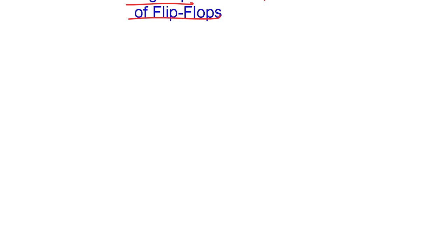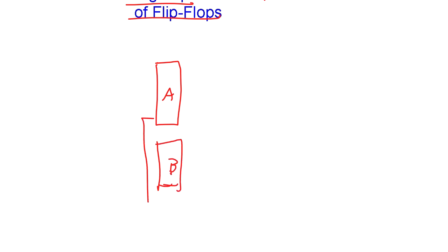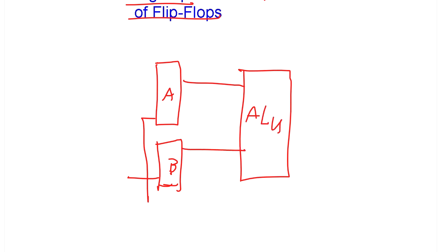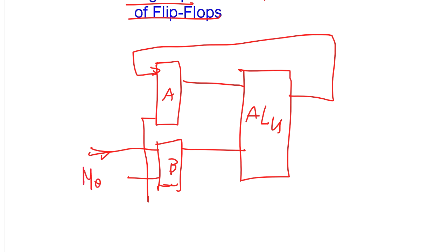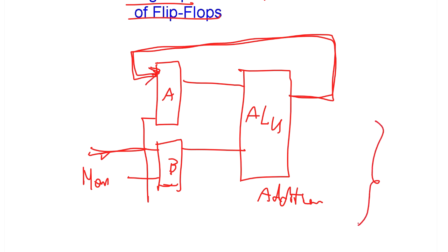microprocessor, what happens is you have many registers, register A and register B, and you have the same clock going, and both go to the logic ALU, right? Then output is going to go back to A, and the B fetches another data from the memory. So you can do, say, addition of data from memory. Say you fetch one by one and add it, accumulating into the register A. So this is CPU, right? So now it's very close to understanding the nitty-gritty part of the CPU at the logic level. Okay, so that's the ultimate goal for this project.